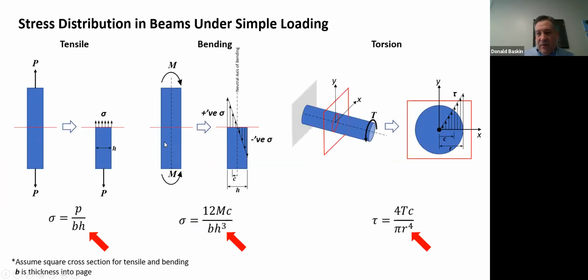Another thing to know is that when you have bending and torsion, the stress is much higher as you go away from the central axis, where the stress is 0, all the way out to the far skins. So the further you go away from the center, the higher the stress gets until it hits a maximum on the complete outer boundaries of this beam in bending.